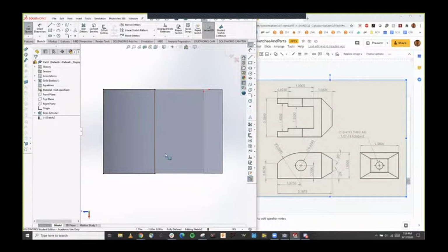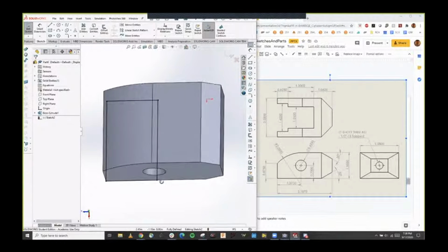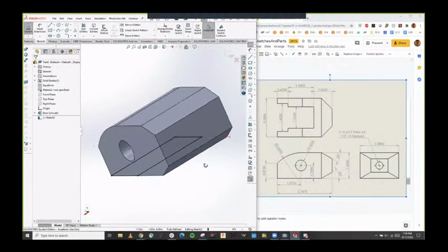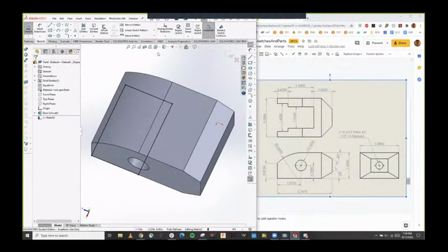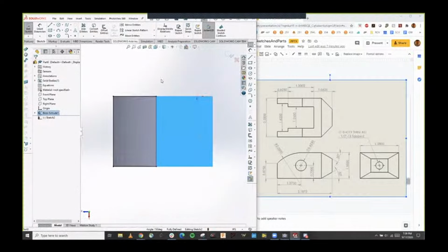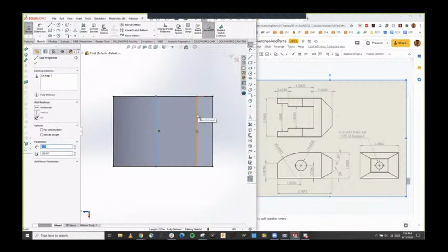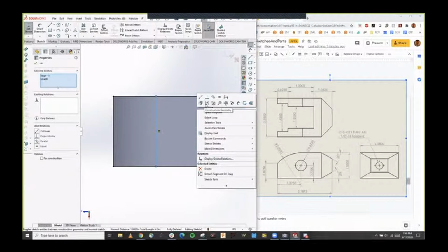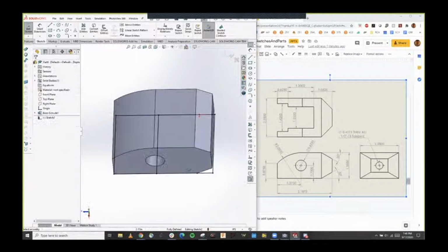What this does is that from the sketch plane, the view that I'm in, it projects the line segment down. So you see from that curve, we got a rectangle of points projected exactly down. Pretty neat. So if I do that for the rest of this, I'm going to select this part and this part, convert entities, and now I'm going to make these two center lines construction geometry by selecting them, right-clicking, and this is how you convert stuff to construction.